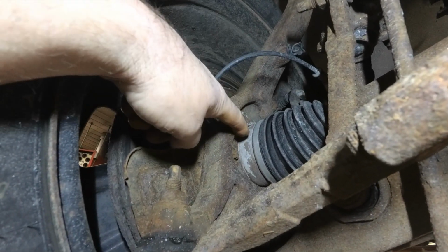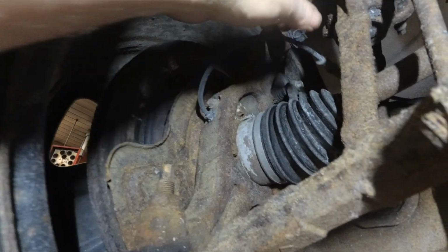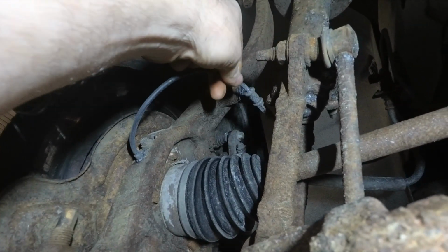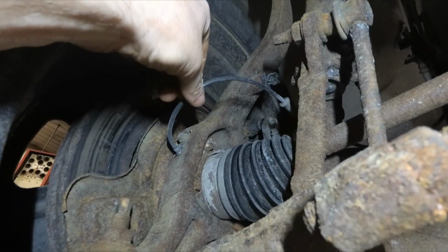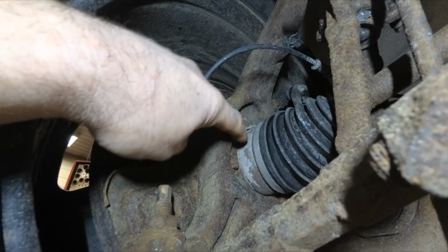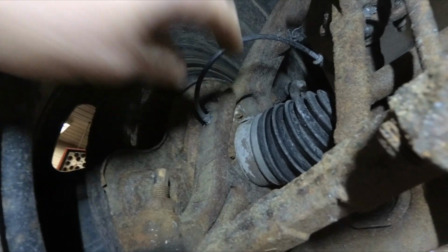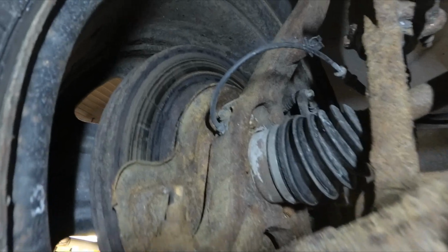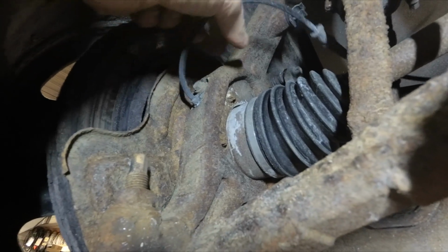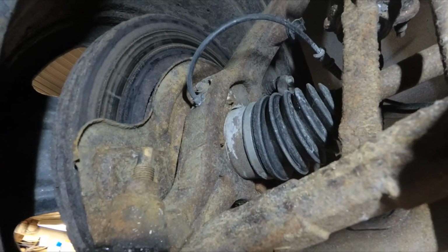Now there is a reluctor inside here on the CV shaft, if I'm not mistaken, very similar to the rear. I see this little clip was out of place here, but that shouldn't have affected it, and the wiring looks like it's not damaged, but it's hard to tell. I'm wondering if this could have the same problem as the right rear had, where the speed sensor reluctor is likely part of or on the end of the CV shaft, and it's actually failed. Now taking this speed sensor out of here might be difficult because this is cast iron and it rusts, but then again sometimes they design them so that they do come out.